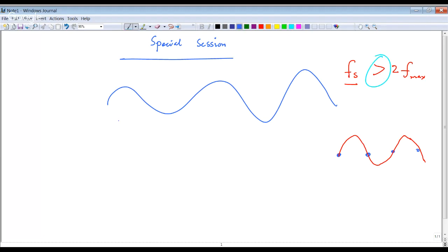Basically, you have a pulse that you sample. You have a continuous time signal here. You sample at a certain rate fs, which is more than twice the maximum frequency contained in the signal. And this is how one can think about it. This pulse is very, very narrow, the time is very small, and you can treat this almost as an impulse. I'm just going to put your samples here, so on and so forth. So these are your samples, at these points, capturing this, this, this, and so on for the rest of the signal.